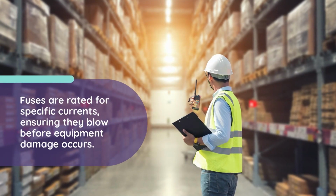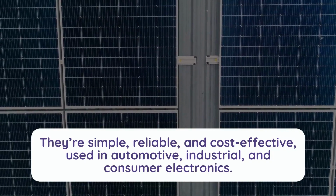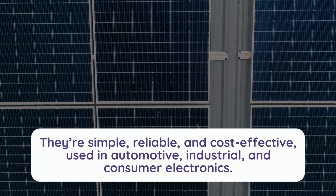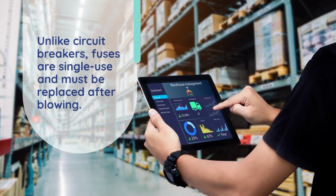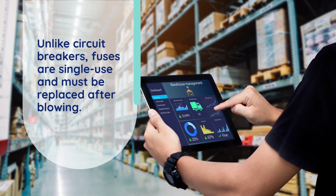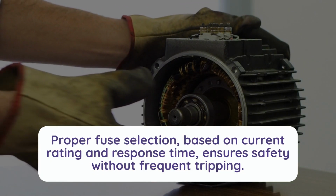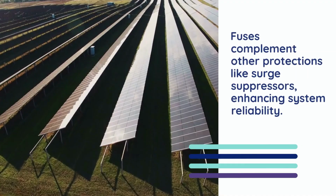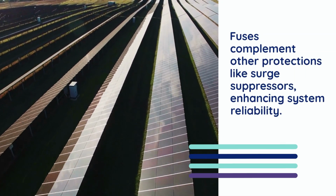Fuses are rated for specific currents, ensuring they blow before equipment damage occurs. They're simple, reliable, and cost-effective, used in automotive, industrial, and consumer electronics. Unlike circuit breakers, fuses are single-use and must be replaced after blowing. Proper fuse selection, based on current rating and response time, ensures safety without frequent tripping. Fuses complement other protections like surge suppressors, enhancing system reliability.